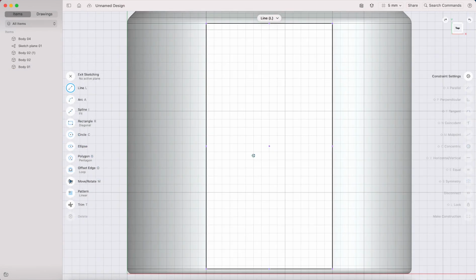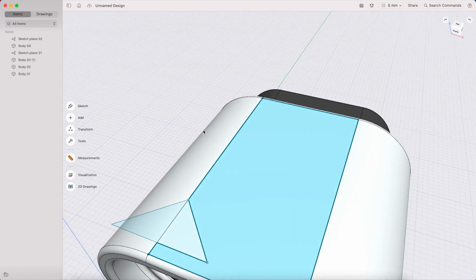So just click on the face, press the spacebar. It gave me this top, and I can use a line perhaps to draw a triangle, right? So let's click on any point here on my grid. So I closed the lines. If I close the line, it allows me to draw a shape. If it's not closed, then these are only reference lines. So now I have my triangle here.